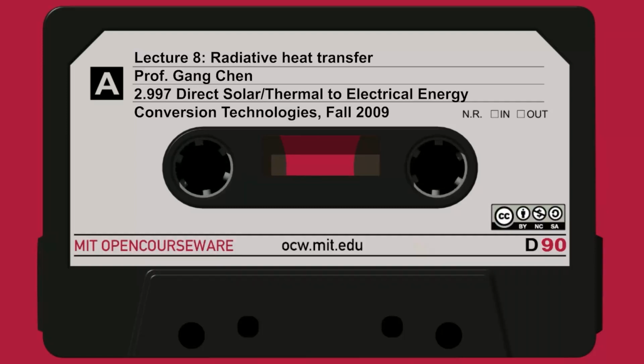And from Earth to the Sun, how much radiation leaving Earth reaches the Sun? That's the fraction. This is the fraction of radiation leaving the Sun that reaches the Earth. Here is the reverse, and because the Sun's cross-section area is larger, the view factor from Earth to Sun is larger. Fraction-wise, more radiation leaving here reaches there than the other way. So first, you check that reciprocity is satisfied.